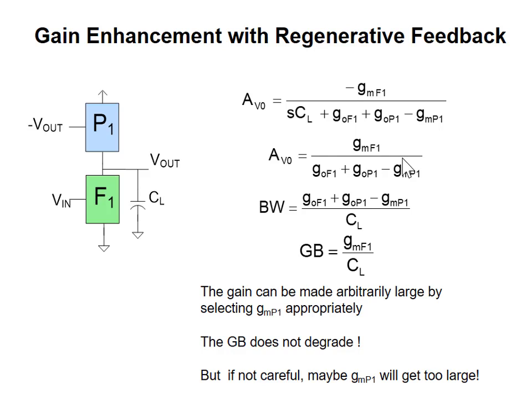So what do we build amplifiers to work with? We build op amps as if they have infinite gain in the region we're operating them. These poor amplifiers that we build don't have this high gain. What's important is the gain in this region here. It's horrible. It's dropped way down from what we had for our DC gain. And furthermore, it changes with frequency.